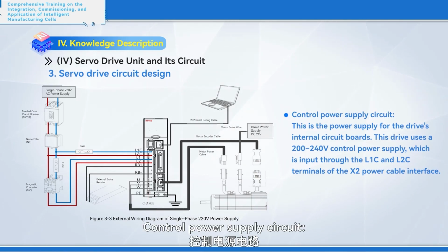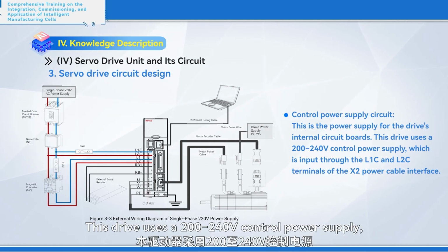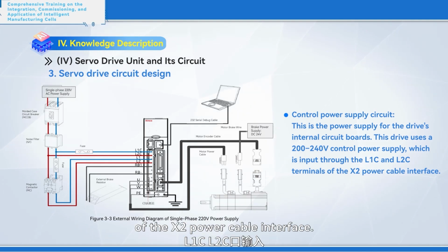Controlled power supply circuit. This is the power supply for the drive's internal circuit boards. This drive uses a 200 to 240 volt controlled power supply, which is input through the L1C and L2C terminals of the X2 power cable interface.